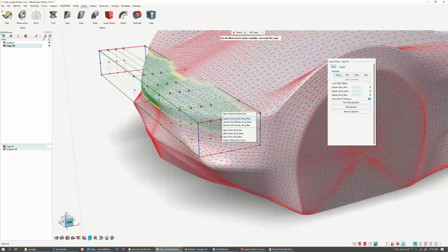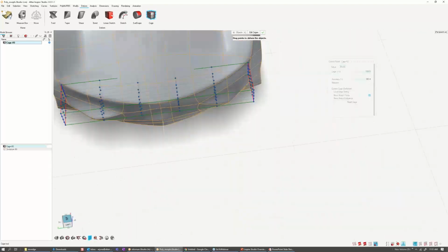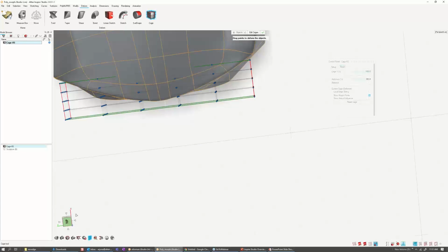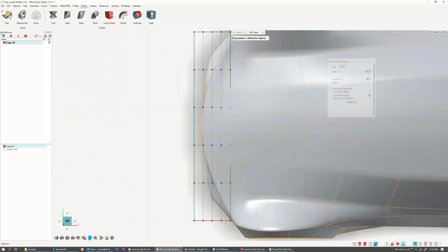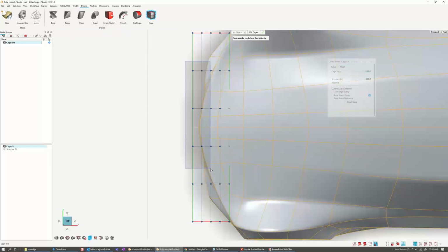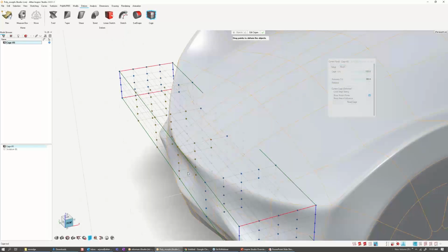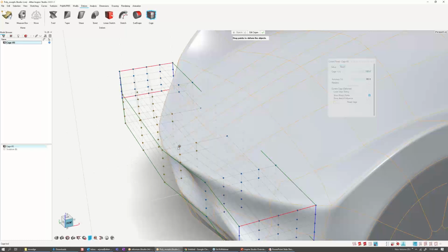So now I can go to the morph phase, and when I select some points, let's say if we select a bunch of points here. Let me look at the top view. So let's say I just want to morph some points here. So I'm going to select these points. And when I move them, I'm just using the same vertex movement, moving only those points on my